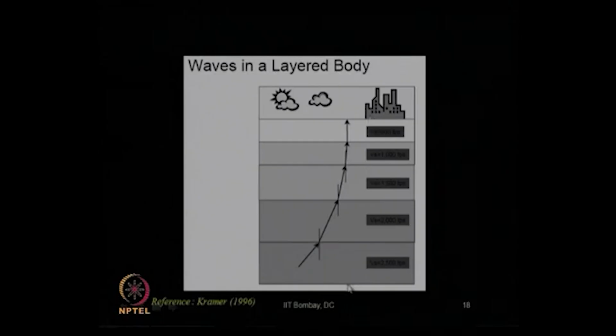But in a typical soil strata in practice, we get softer layer to stiffer layer, so the shear wave velocities typically increase in ascending order as we go deeper from the ground surface. That indicates if an incident wave with a large inclination angle is incident like this, the refracted or transmitted wave in the next layer, which is softer compared to this layer, will be more towards the vertical direction.